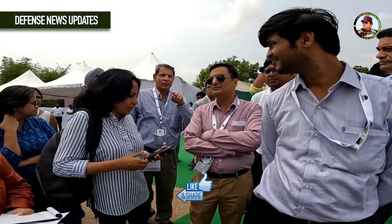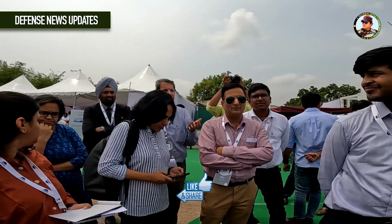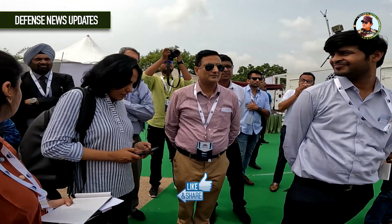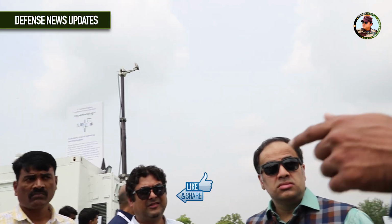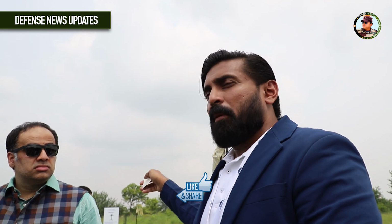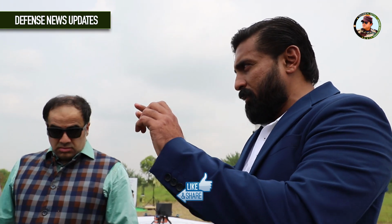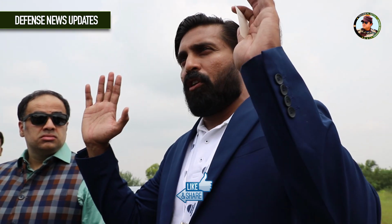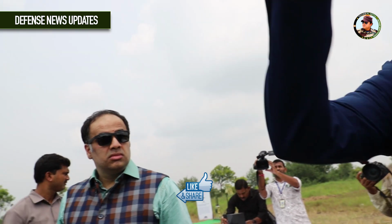This one-on-one doctrine of kamikaze operation, is it really worth it? Can you not scale up the combat capabilities of the platform? Actually, I would say the jammer is a very interesting thing, right? I'll ask you this simple question. Today, when you see the demo, we'll actually jam this drone. The programming in this drone clearly says that when you jam it, it goes back to home, right? When you jam it, that means it's jamming the RF signals of the drone, so the drone is not receiving anything from the ground station, so it's programmed to go back home. Now it's very easy to program a drone saying that the home location is the target. So even if you jam it, it'll just go up and go to the target, right?